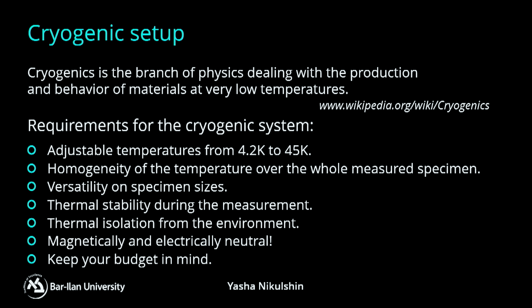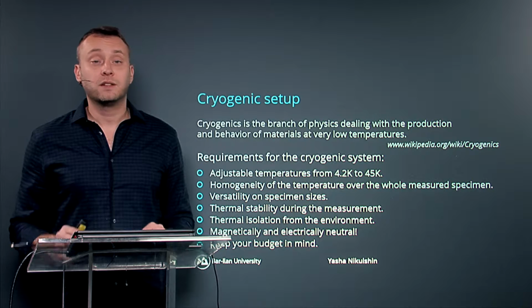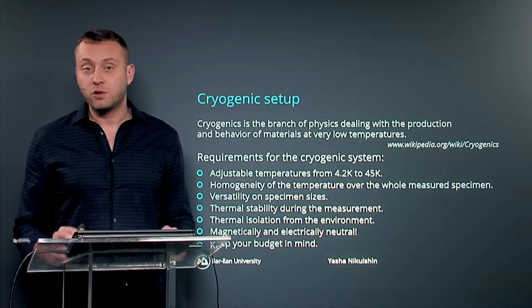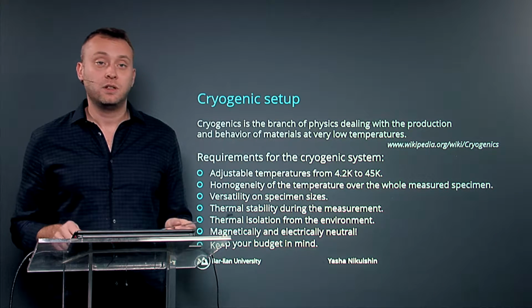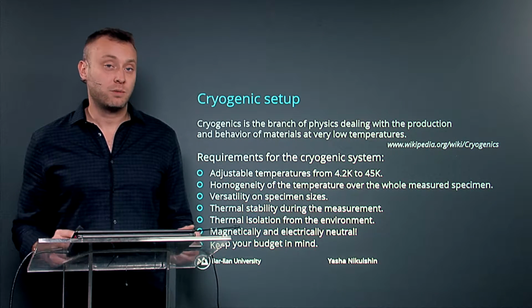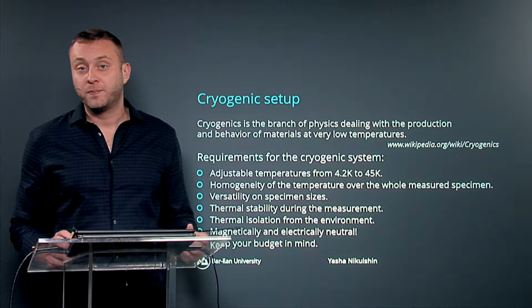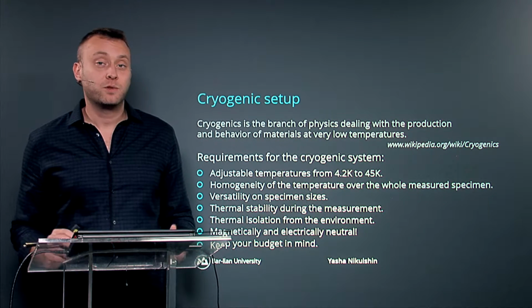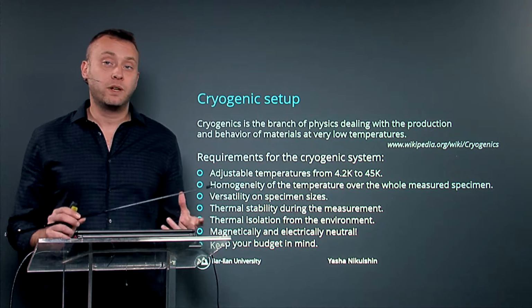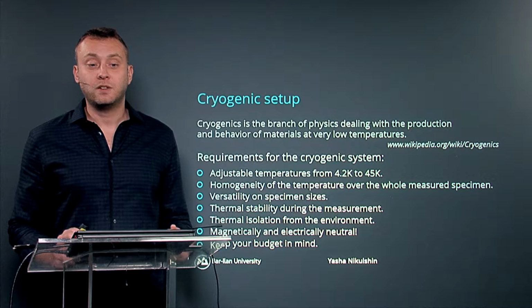Homogeneity of the temperature of the whole measured specimen. Because a superconductor's properties are very dependent on temperature, we need to assure that the whole specimen we measure has a homogeneous temperature. Versatility on specimen sizes. We might measure different sizes of superconductors, so we have to prepare the whole setup for different sizes and geometries.